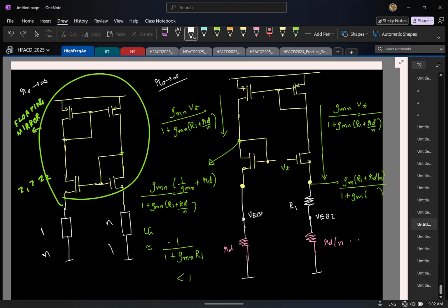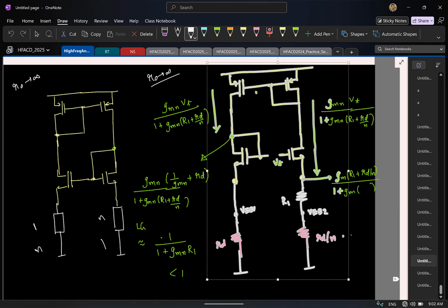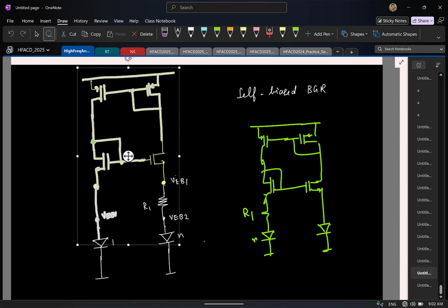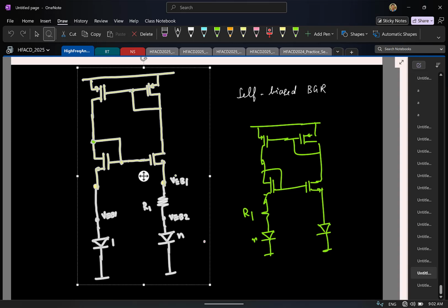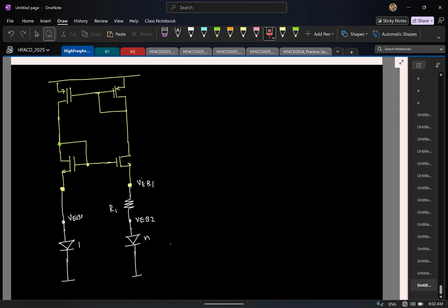And of course this is the final circuit we had, and of course this is not complete. Let's just complete it and move on. So this is the thing, and here if this works correctly, these two voltages will be equal. So this is VEB1. So the current flowing through this will be the PTAT current because the current is a difference between the VEBs by R.